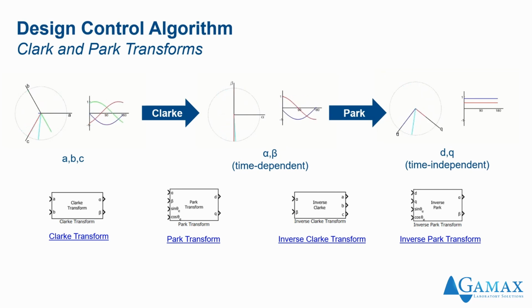With the help of the Motor Control Blockset, we have the opportunity to design and simulate motor control algorithms with computationally efficient implementations of Clarke and Park transformations. And this is also true for inverse Clarke and inverse Park transforms with pre-built off-the-shelf blocks.